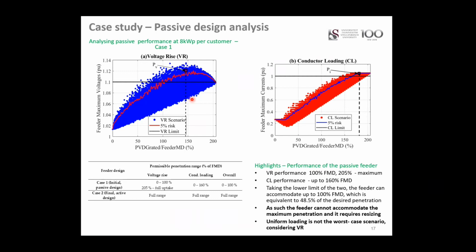That's probably associated with increasing voltage unbalance. As the voltage unbalance increases on your feeder, there's also an increase in voltage rise. So if you just size at this last position without considering the incremental performance of your feeder, you are likely to get wrong feedback in terms of your sizes.